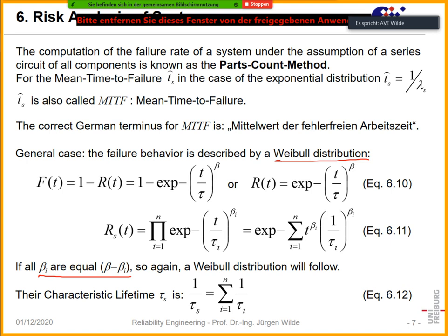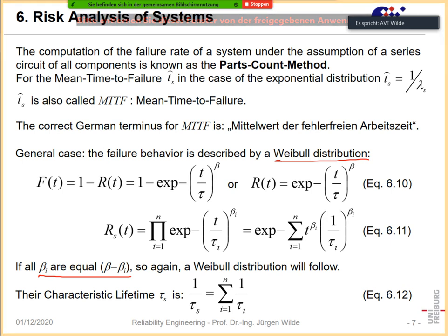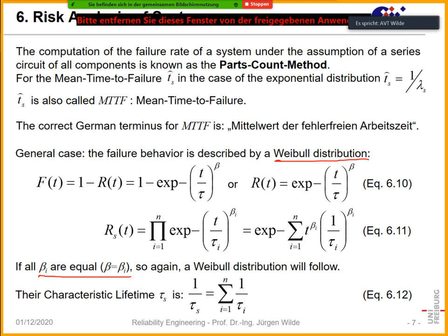Okay, that's for today. And what I was showing you was the most simple case, how we can compute reliability characteristics for systems. So it's series systems, and we either have to take the assumption that in such systems we have exponential distribution, or we have Weibull distributions where the Weibull modulus is the same for all failing devices.